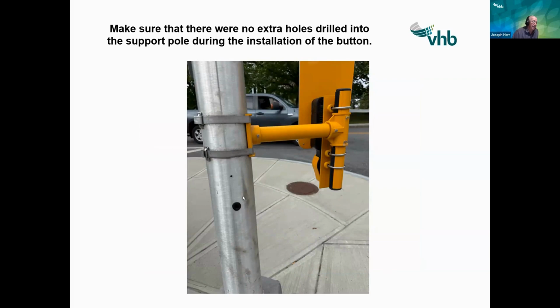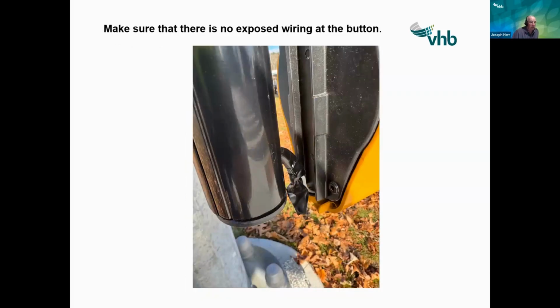The industry does have devices to be able to put that in there, but you don't want that left open where water can get inside the pole. Next, you don't want exposed wiring in here. This one has wiring that comes in with duct tape. Nice try, but this will be a maintenance issue down the road. This is not acceptable during an inspection, and it has to be taken care of so you don't have any exposed wire between the support bracket and the button assembly itself.